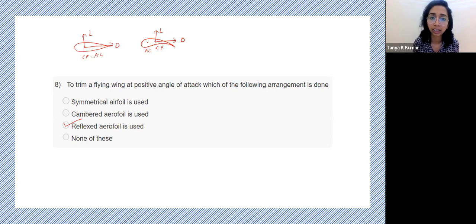So now when we represent our aerodynamic forces at this point, we transfer the forces. We transfer lift and drag here, but it also comes with a moment, a nose down or pitch down moment in this case. So your Cm, that is the pitching moment at AC, is negative. Here in this case, CMAC is 0. There is no moment at this point. It only comes later when the tail lift forces are generated. But at this point, for a symmetrical airfoil, there is no pitching moment. But for a cambered airfoil, you have a negative or pitch down moment happening here.